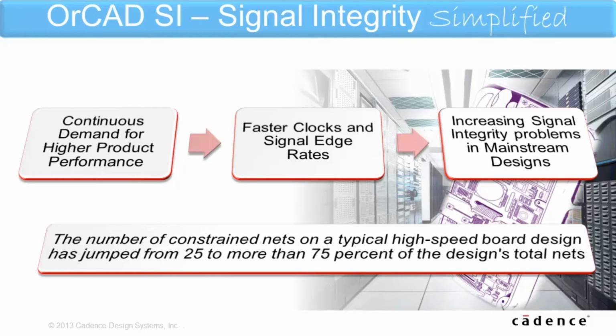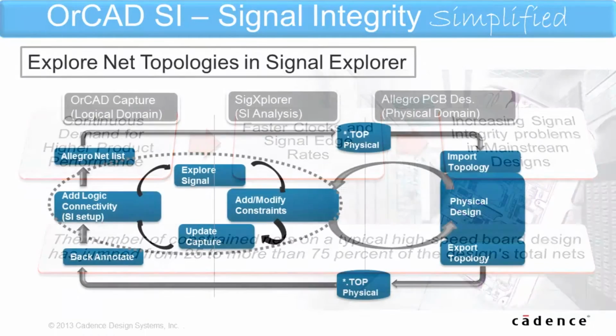It is also unrealistic for every design engineer to develop signal integrity expertise. Typically, design nets get categorized into signal integrity critical, which require the attention of signal integrity experts, and signal integrity significant, which are more easily constrained by electrical engineers.